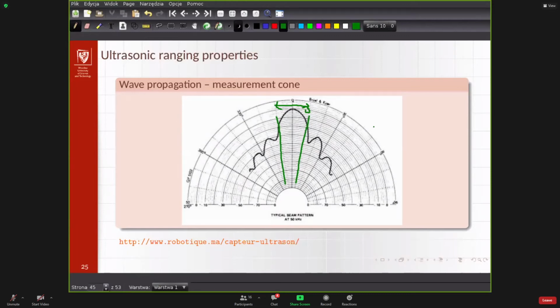In robotics, a disadvantage that appears is that the measurement is quite long. So if you want to measure in different locations with multiple sonars, as you could see, when you have an object 3 meters away, you need 20 milliseconds to get the data and the measurement back.